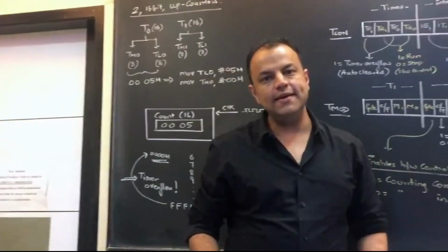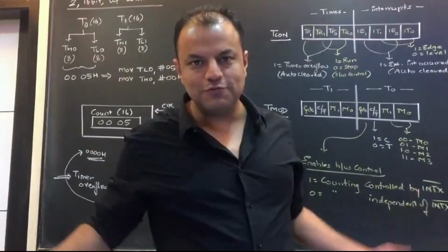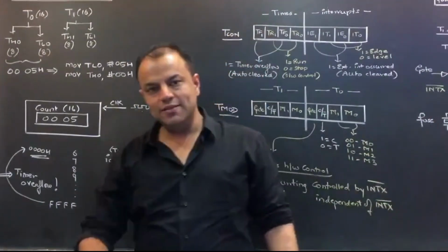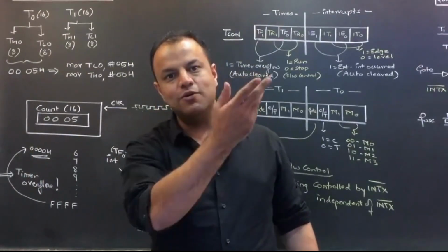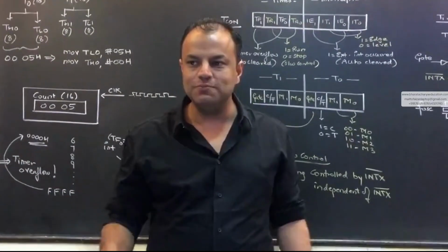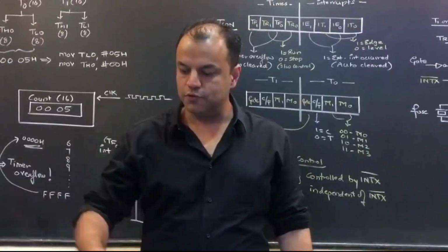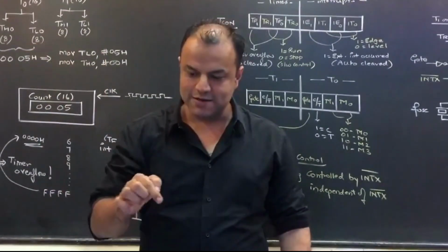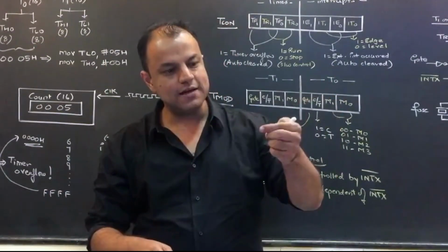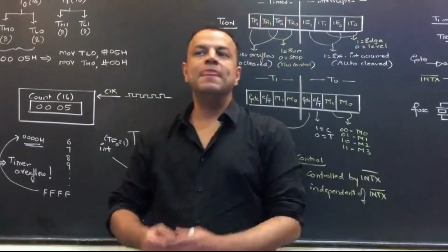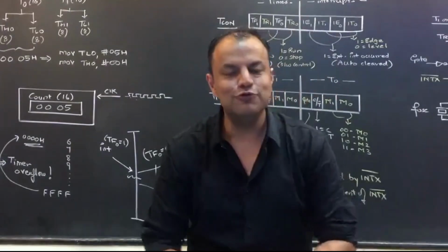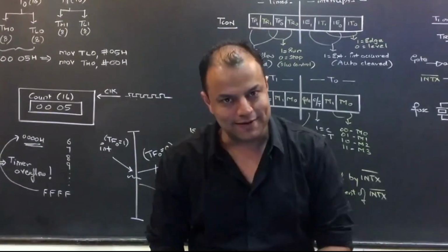So students say, then what is the purpose of this flag? Instead, when the timer had overflown, it should have sent the interrupt and we would have gone to the ISR. That would have been so simple. Now, the timer overflows, makes the flag 1, sends the interrupt. We go to the ISR. The flag automatically becomes 0. So why do you need this flag? These flags are used to store the pending status of interrupts.